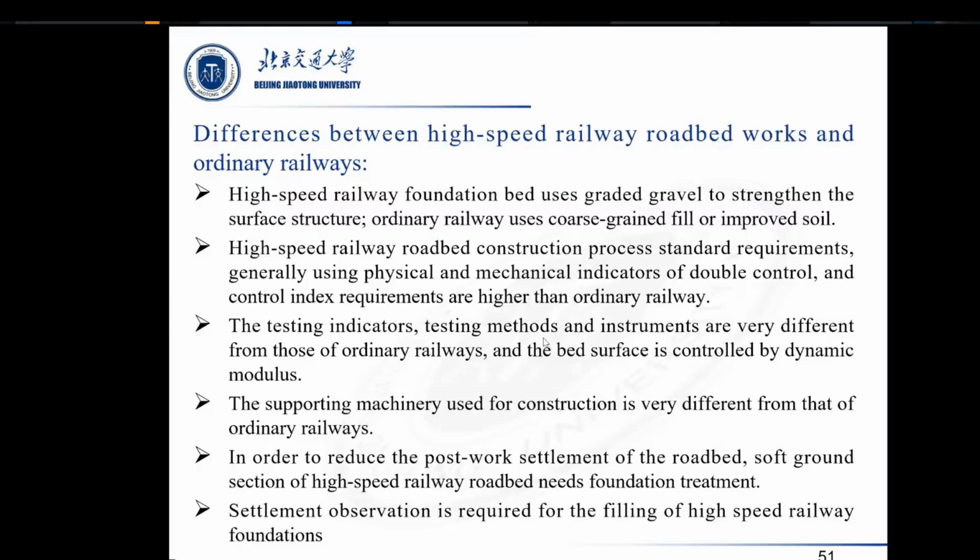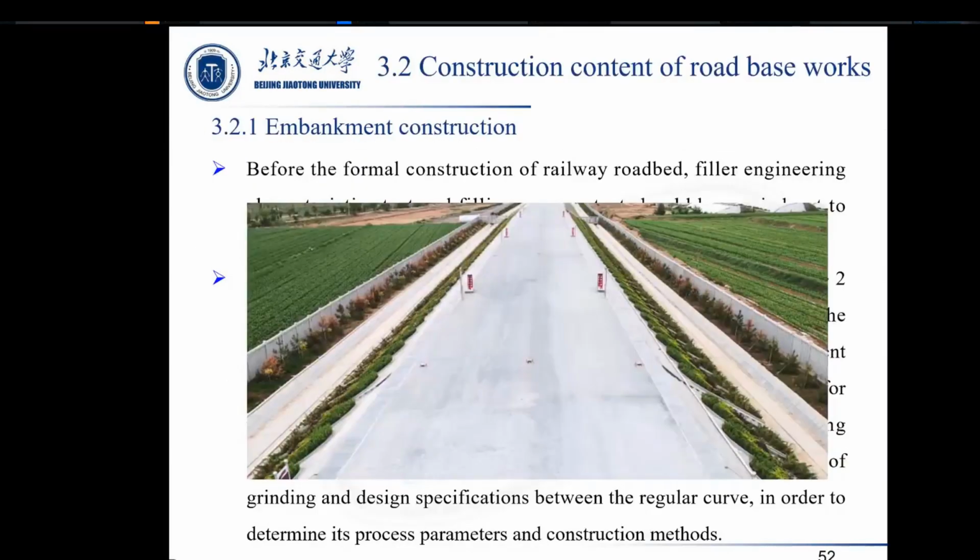Generally we can use the test section before the full-scale development of railway roadbed earthwork. For each type of fill, engineering characteristic tests and compaction process tests should be carried out to determine the corresponding compaction scheme of the roadbed.